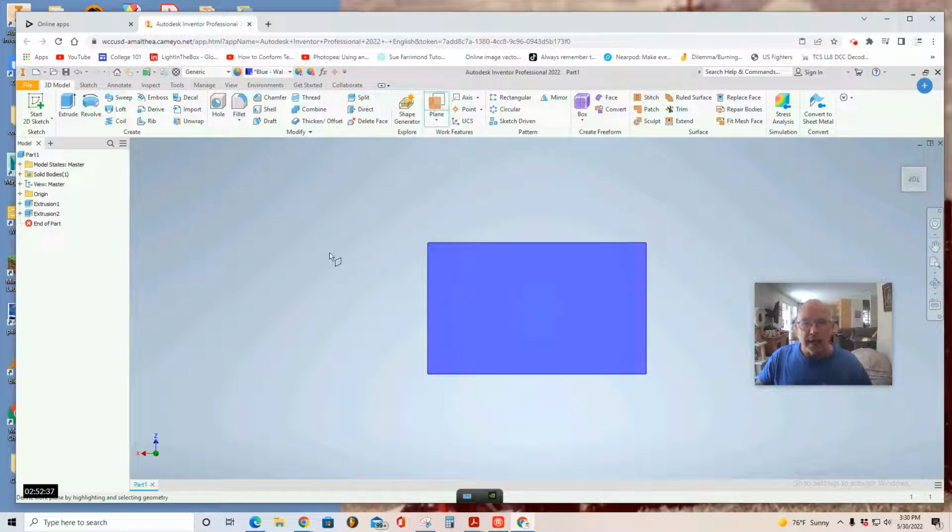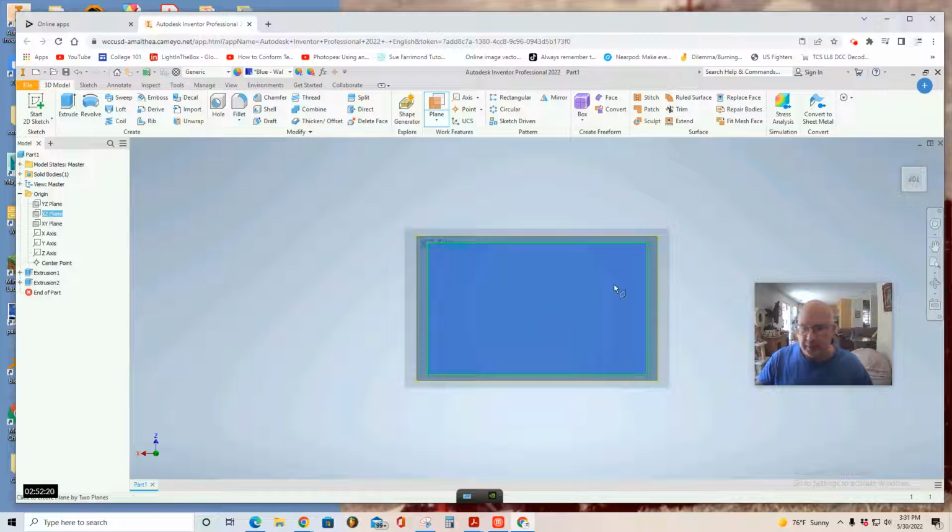and that's where I'll rotate and revolve my rocket ship that I'm going to put on the top of my Duplo. I select plane, I move to the left where I see the origin folder, click the plus sign, and look for, in this case, it's going to be the XZ plane, which is facing me. And I'm just going to grab that little yellow circle in the corner and push it momentarily to see if I get the 0, 0, 0 to pop up, and then click the checkbox.